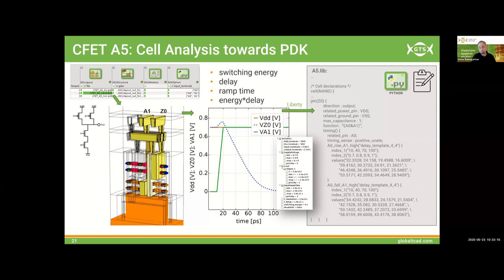So you need a PDK that is usable for you to do these choices. And this can be generated using this TTCO approach. So we have our pre-selected technology parameters, or our technology assumptions, we have our design assumptions, we can run the machinery and basically generate a library file that you can then later use for your studies on a block level or even a system level, and give you some design advantage and maybe some time back, because the turnaround times are really a big challenge for the whole industry.